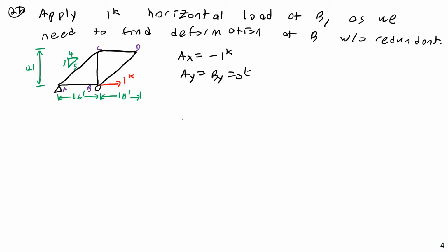And so member virtual forces, in other words, what's going to happen here is that the unit load comes in horizontally on joint B, and just is delivered straight through member AB and is delivered directly as a reaction at joint A. So our virtual member forces are as follows. Or maybe I can write a table.